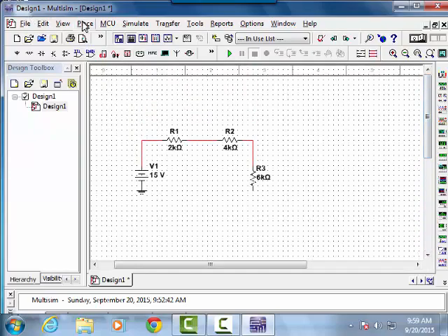You do that again. Place junction. And if I click there, I actually put a node that I can connect to. Just going to shove that up there a little bit. So I can now connect to that node because I've put a junction place there forcefully. So, alright, now I have my circuit nice and neatly drawn. The next question will be, how do I simulate it? How do I get currents and voltages in this circuit?